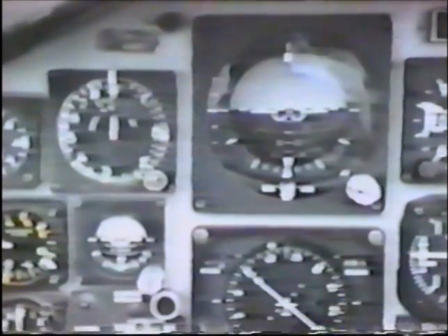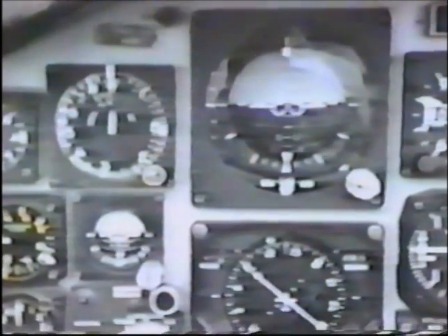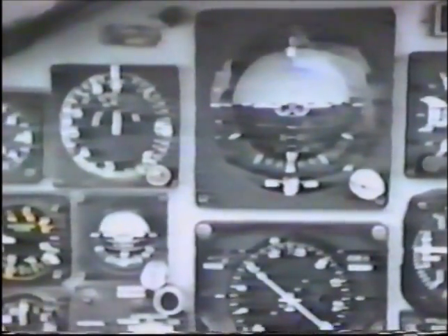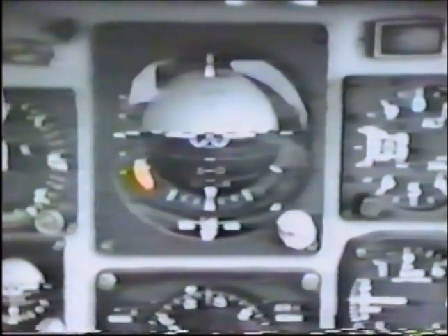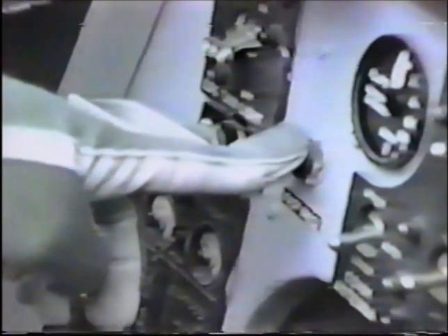Next, check your main and standby attitude indicators for off flags or precession. An off flag in the 8 o'clock position of the main ADI will appear whenever power to the instrument fails or is interrupted. Precession in the main ADI can be corrected by pressing and holding the fast erect button, which will erect the attitude indicator at a rate of about 15 degrees per minute.